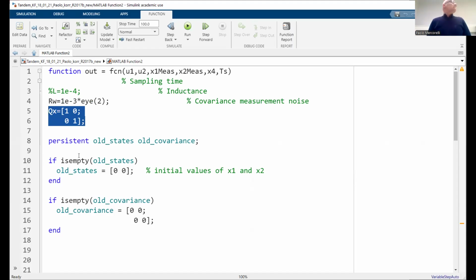I told you a lot about how we can do it, considering the meaning of changing Q and R. Of course, in the project, very often we do not always do it manually. We do it manually in linear systems, because once tuned, we don't need to retune. In the nonlinear system, we use PSO, neural networks, other intelligent algorithms to tune the Kalman filter. Here, it's always the same.